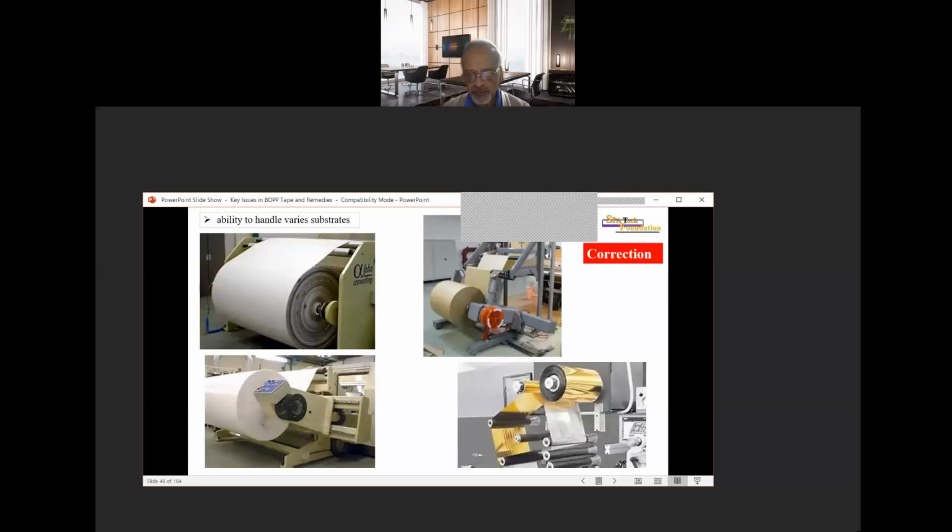Here is a photograph of a laminate of golden metallized film with silicone paper. The benefit of square winding is you can control the trim losses to a minimum. The ideal trim width could be around 5 millimeters on both sides, and this is possible if and only if the winding is square.